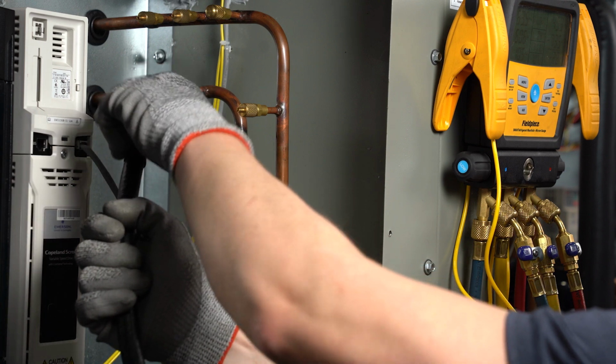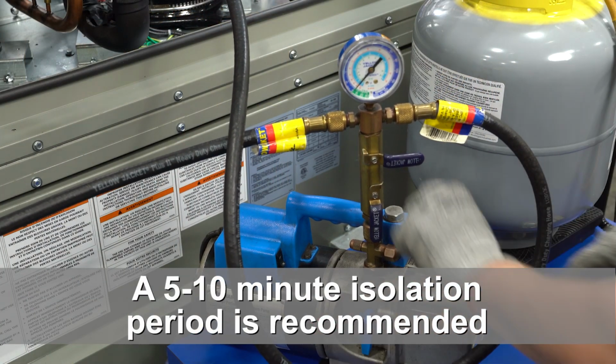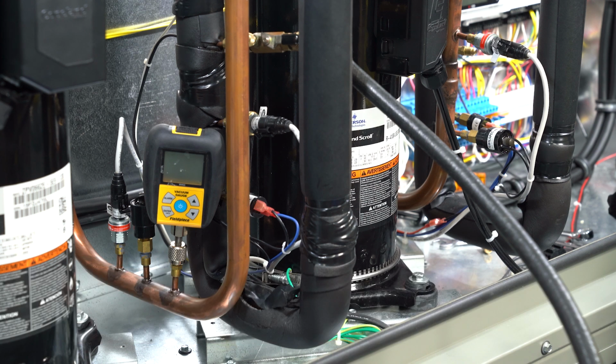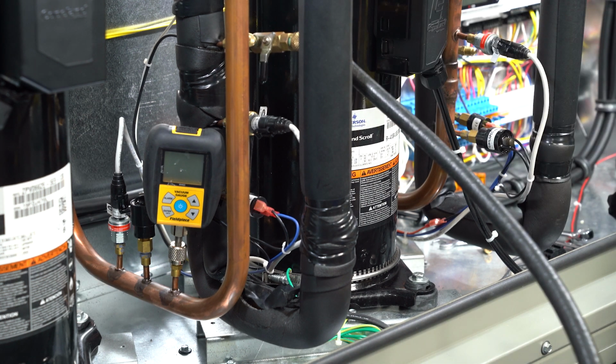Hook up hoses to vacuum pump and energize the pump. After proper vacuum of less than 500 microns has been achieved, which may take several hours, isolate the vacuum pump from the system by closing service valves. If micron level remains below 500 microns, the system is now ready for refrigerant.